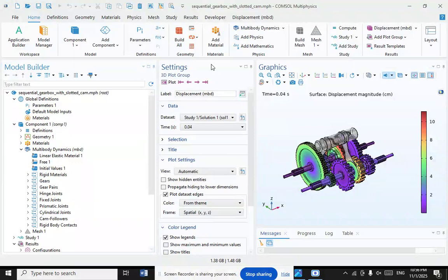In a transmission for longitudinal engined vehicles, for example, most rear-wheel drive cars, it is common for the input shaft and output shaft to be located on the same axis, since this reduces the torsional forces which the transmission casing must withstand.